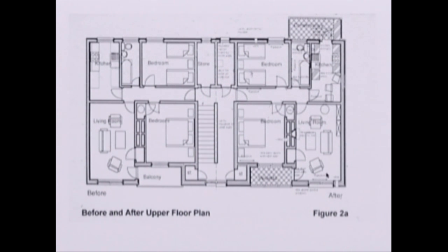So instead of having, as shown in the original plans, radiators in all the rooms, the option that I'm looking at as viable would be to have a heat recovery unit located for all 3 flats up in the attic space, recovering heat from the wet areas, and linked to an air source heat pump. Now there are 2 possible locations for this. One would be in what was originally a fuel store. That means it's accessible still off the common stairwell.